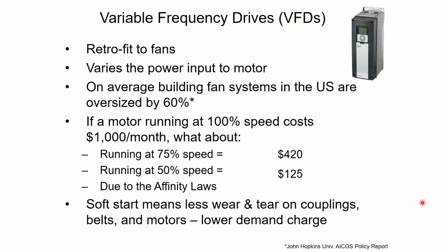So it's more like when you're driving your car and you slowly put the gas pedal down as you accelerate from stoplight to stoplight, or at least that's how I drive now, right? When I was 17, that's not how I drove. I would just gun it. At the next stop sign, I'd slam on the brakes, gun it, slam on the brakes, right? That's a normal rooftop unit's fan today. But if you put a VFD on there, you're driving more like me, a 44-year-old who drives a Prius and tries to optimize his miles per gallon. I'm like coasting to the stop signs, right? So that's what this is going to do for you.